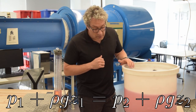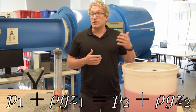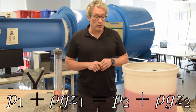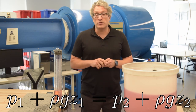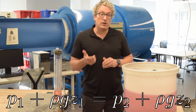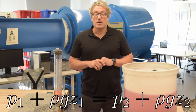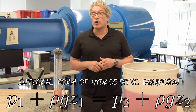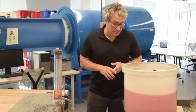We derive the hydrostatic equation by drawing a control volume and comparing the magnitudes of these different forces: a volumetric gravitational force that pulls down, and a pressure force that's a surface force applied all over the control surface. When these two are in equilibrium, the system can be motionless and can have an equilibrium of forces. When we do this analysis, it is relatively straightforward, because we have only two forces existing in the system. The pressure and the gravity are the only two things that we need to take into account, and therefore the only two things that end up in the equation. The final equation we get from this integral analysis is what we call the integral form of the hydrostatic equation, that tells us the differences between properties at two different points in space.